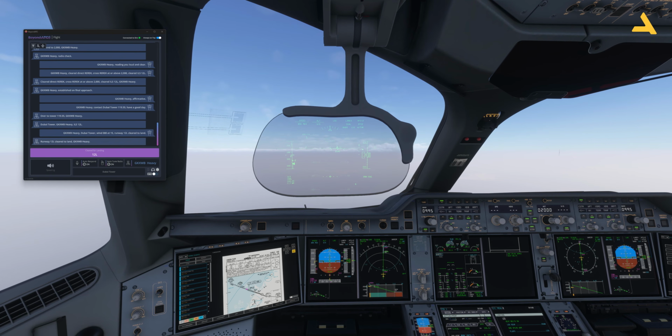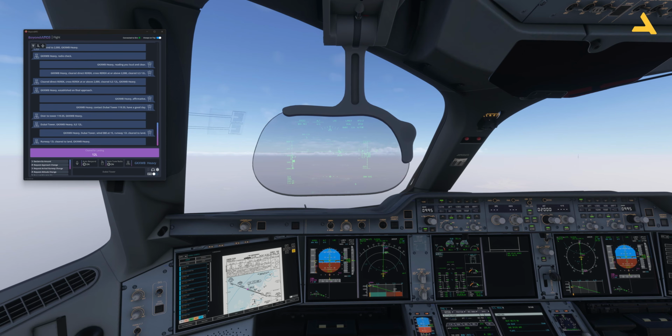I got the clearance for the runway landing. 12 left, cleared to land. Golf Kilo X-Ray Whiskey Bravo Heavy. And now the runway is 8 nautical, roughly 7.4 nautical miles away. At 8 nautical miles, I extended the flaps to position 2.